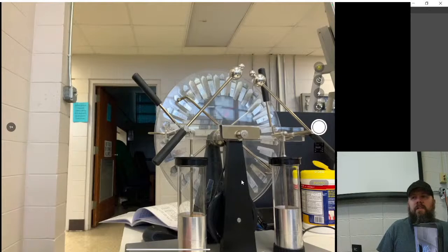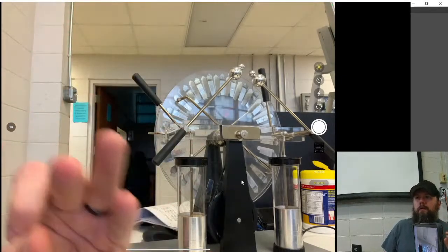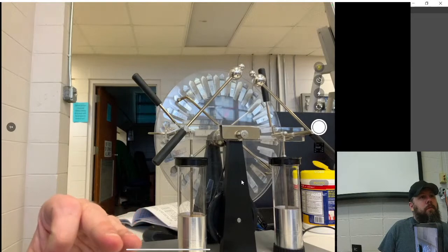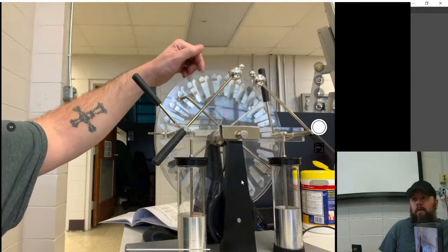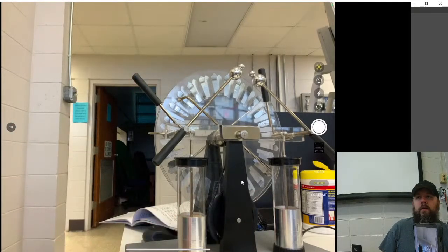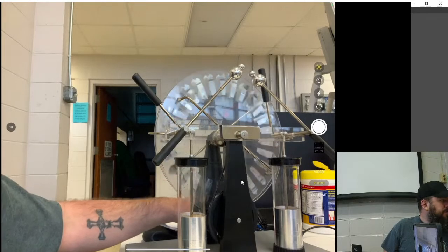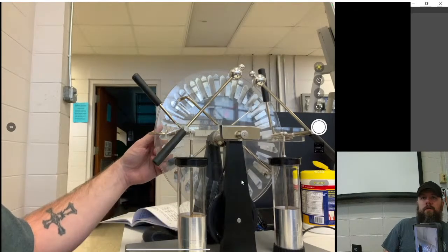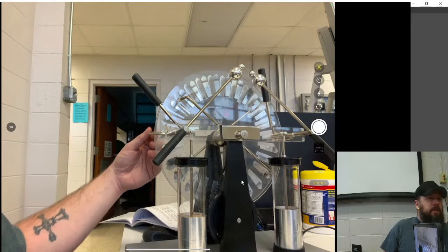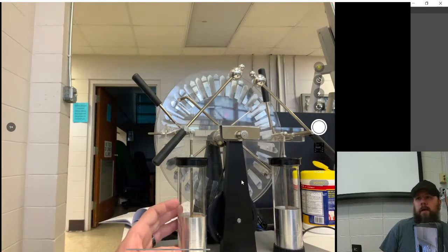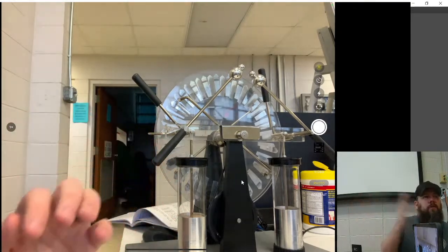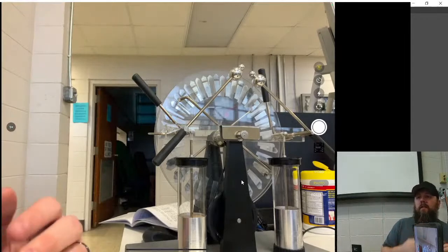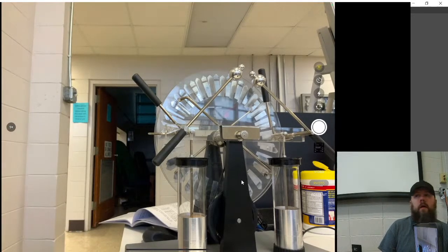That gives a net positive charge to that little plate. Well, what happens when that little positive charge lines up with the plate on the other side? That attracts an electron, doesn't it? And then as it turns, it gets scooped off by this brush. It's just a conductor, and it gets put over here. Then that gives it a net positive charge, right? So it's just going back and forth, causing electrons to get attracted to it because it's got a net positive charge at a certain point, and then scooping those extra electrons off, right?